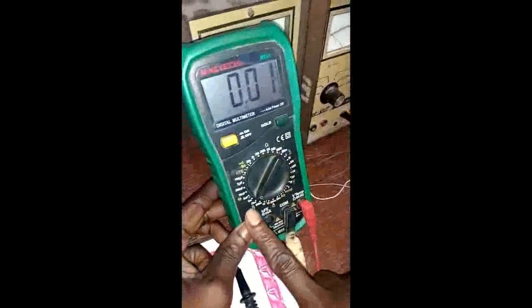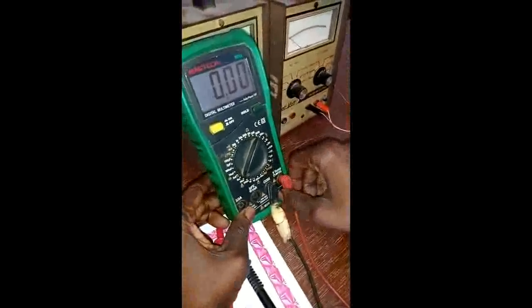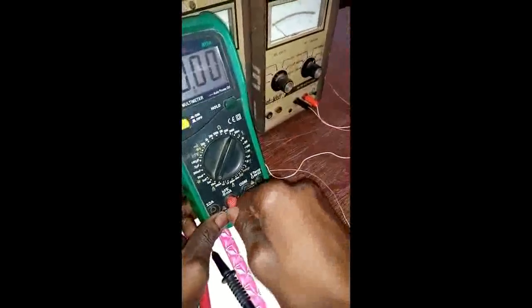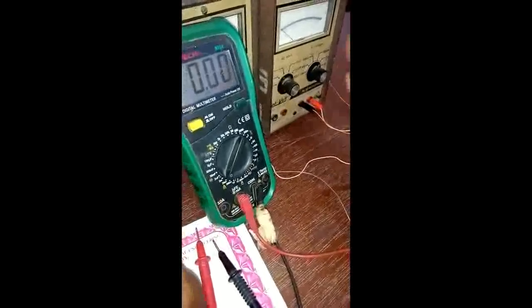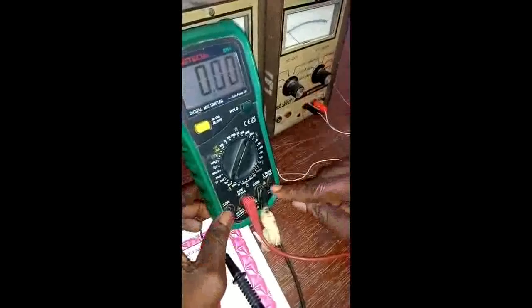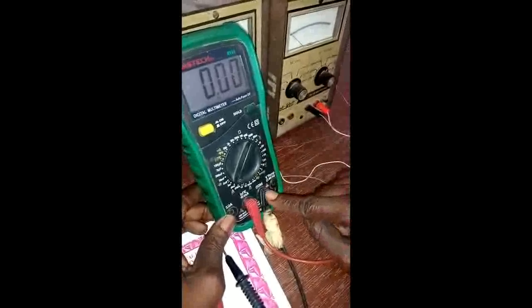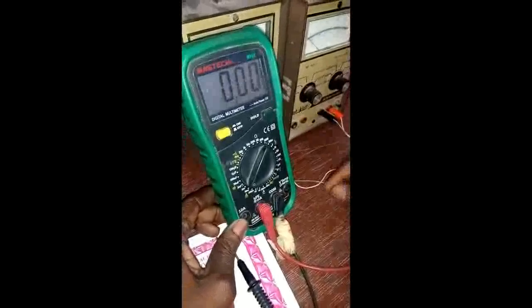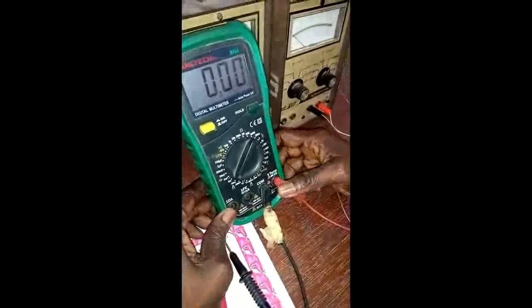For example, if you want to measure DC current, then you have to move this probe from here and connect here to this milliamp ring. That's the only time it's ready to measure current for you. This common is stationary. You don't need to touch this one. So you will now be using this one and this one. Unlike when you are measuring voltage, resistance, and what have you, you have this probe being connected here for the measurement. You can even see from here.